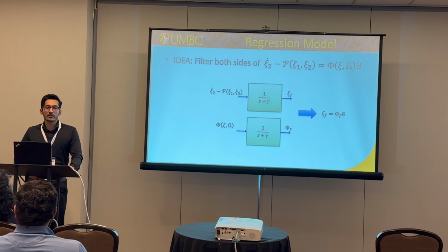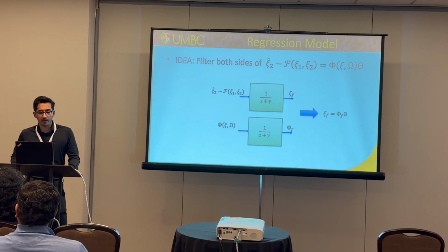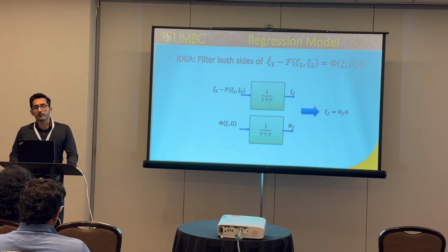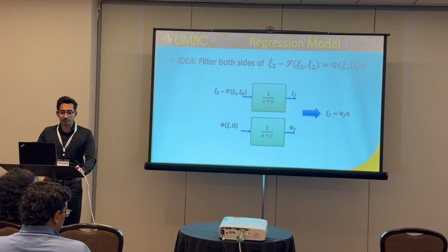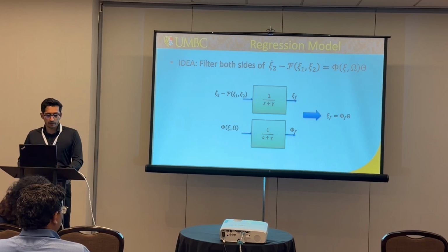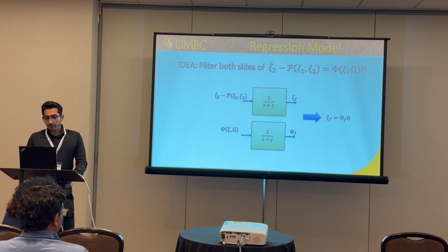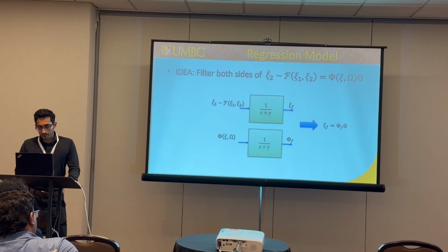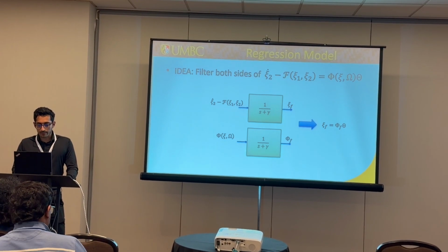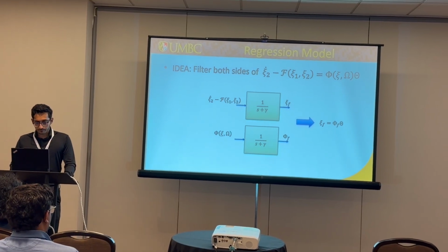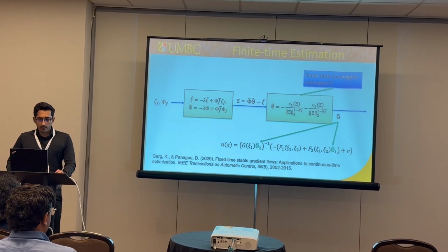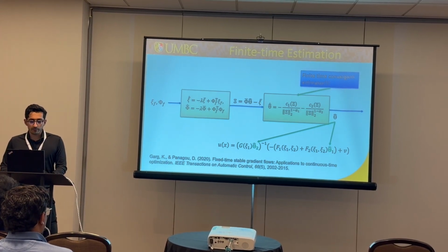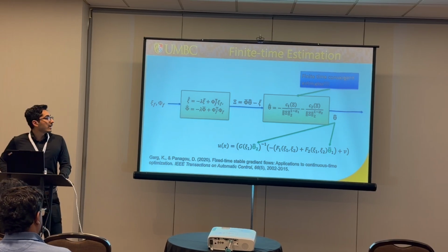In practice, taking derivatives causes problems, like high frequency noise in our system. So we filter them with a low pass filter. It's a strictly proper low pass filter, and we get the filtered signals as phi_f and y_f.